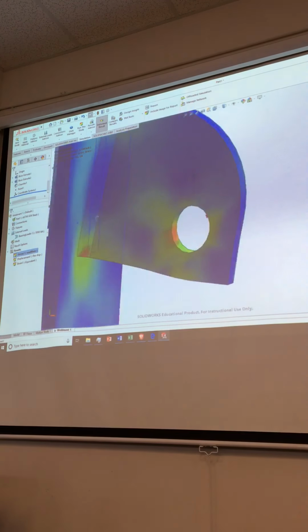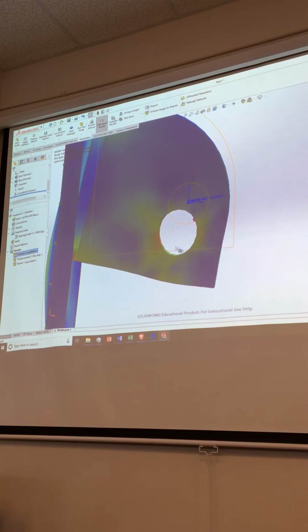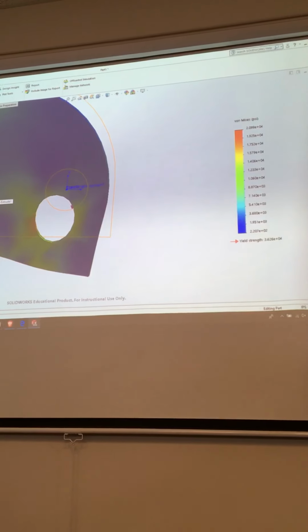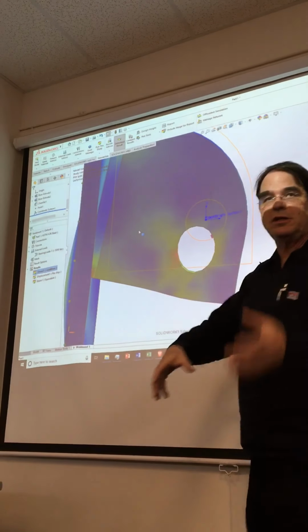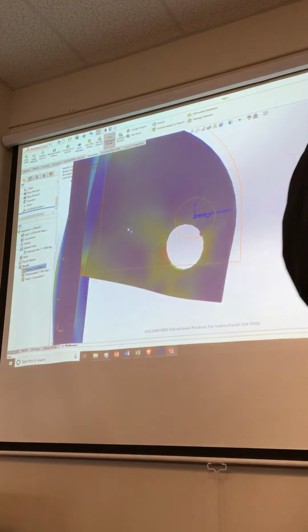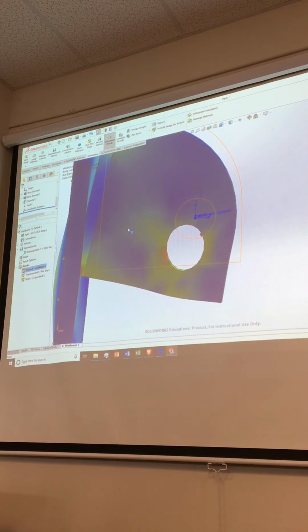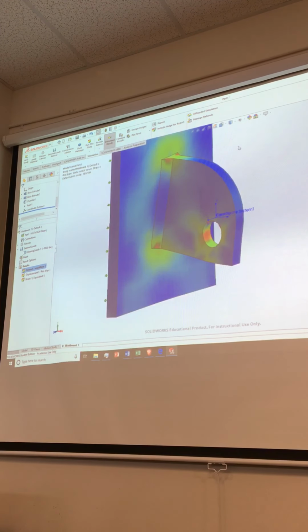And now we get some things around the hole that are starting to look a little better, right? It's trying to distort the hole. It's not perfect. It's letting the hole deform a bit more than it should because we're pushing on it. What's it doing? It's stretching the hole. Probably won't be allowed to do that because there's a pin in there. We could play with the stress distribution and make it circular instead of parabolic. It might work a little better. Doesn't really matter. It's not going to change enough to affect things. Okay, so that's not bad, right? Now, let's see. Well, we got stress concentrations. They're still kind of nasty here, but we know how to deal with those things now.